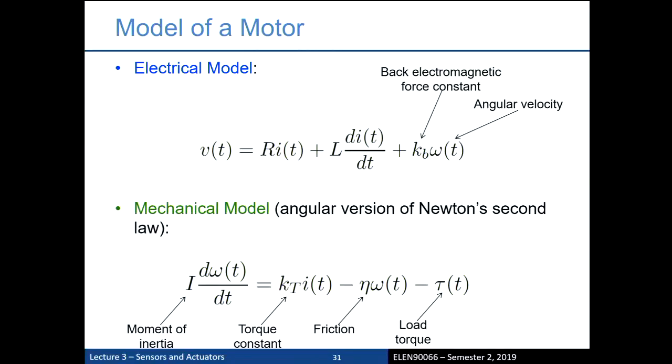If you take a motor and you put a current into it, obviously it spins. If you do the opposite and you spin the motor, you get an induced voltage, and then the current out of that. So motors and generators are synonymous. They're essentially the same thing. And interestingly, up the top is the electrical model of an actuator, a motor. It says the voltage across it is equal to Ri plus L di/dt. For those of you who remember your circuit stuff, that is modelling the motor as an RL circuit, basically. It's got inductance, and motors have a lot of inductance.